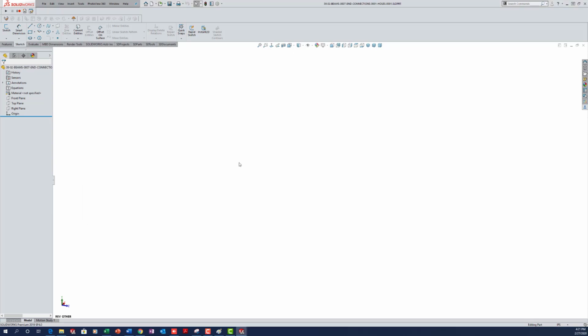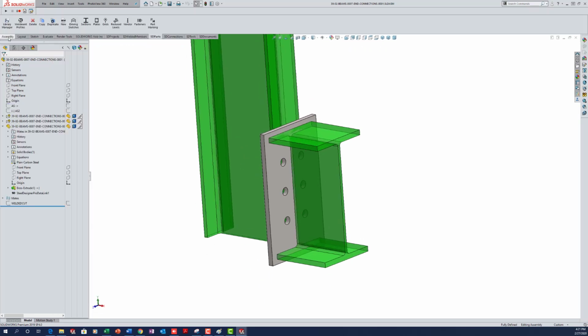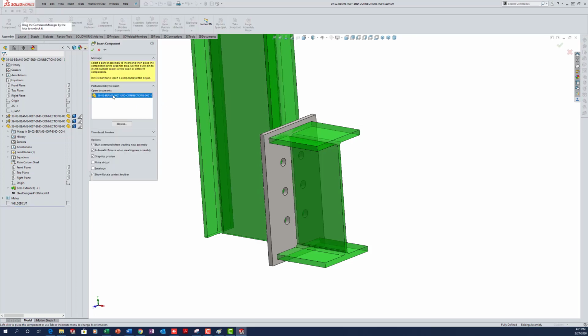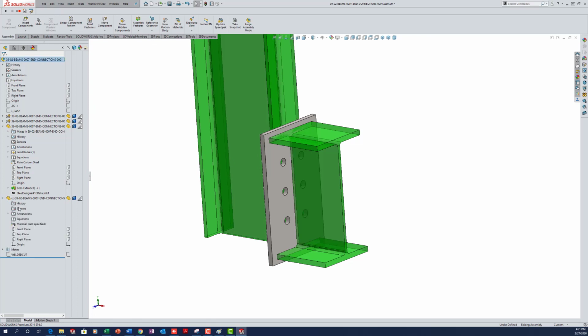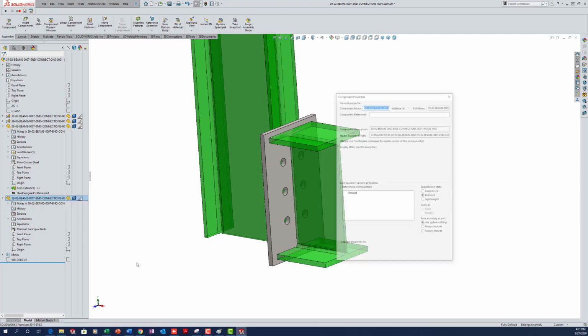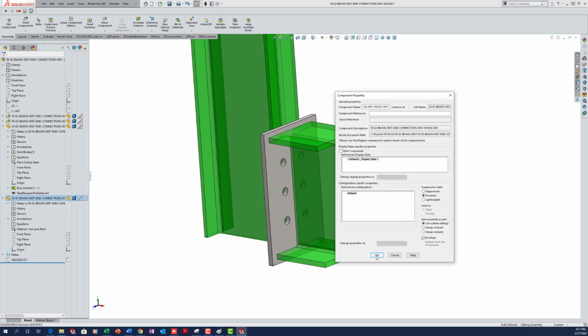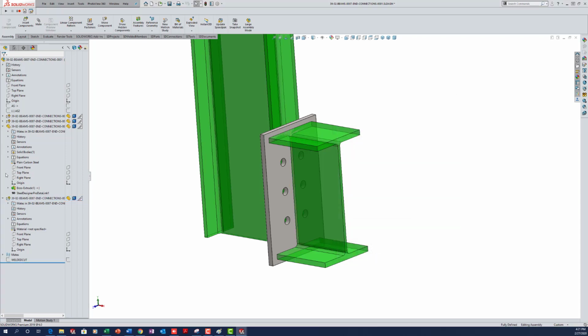And this holes component is going to come in here and be inserted and be attached to the plate. Just dropped it in here. I'll make its origin and the plate's origin coincident. If this doesn't fully define, then edit the mate to align the axis. The holes component will need to be an envelope as well. Change the properties. And just to make it look good, I'll put all the envelopes together.